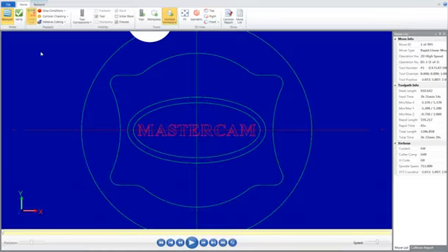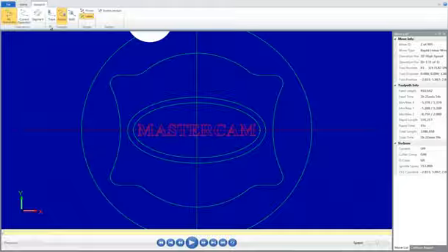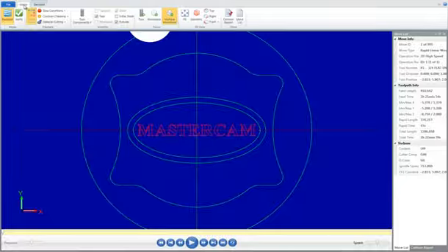As you backplot toolpaths, Mastercam displays additional information such as the X, Y, and Z coordinates, the path length, the minimum and maximum coordinates, and the cycle time. It also shows any collisions between the workpiece and the tool. From here, select the Backplot tab and enable the following settings: All Operations, Follow, and Leads. You can now select the Home tab. Ensure that Tool and Workpiece are enabled. You can now press the Play Simulation button.